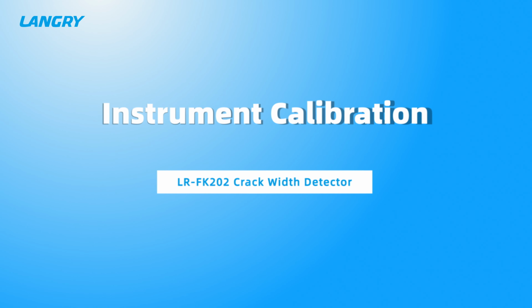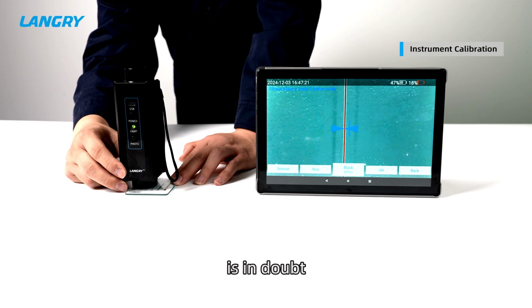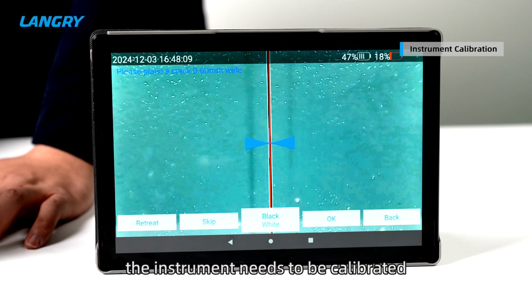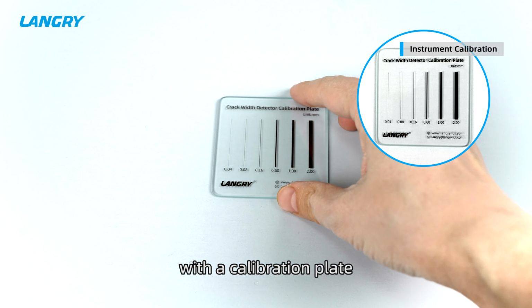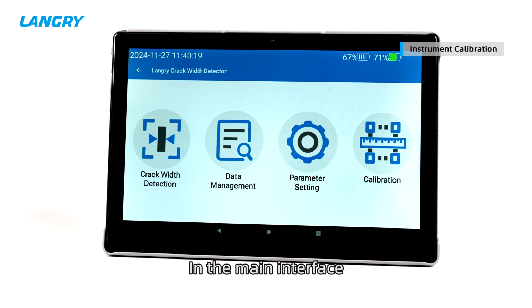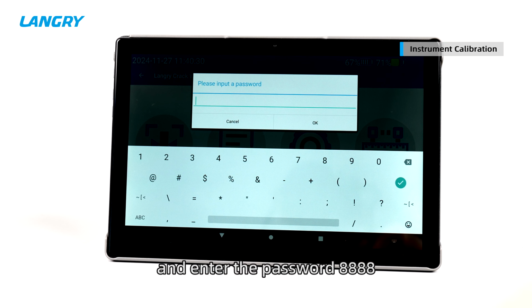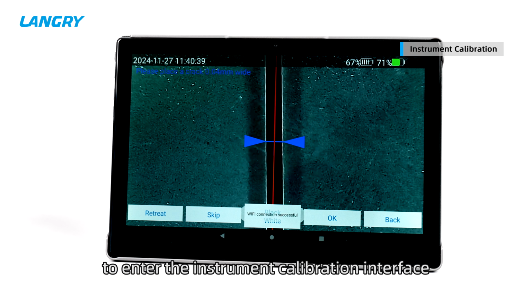7. Instrument calibration. When the observed value of the crack width is in doubt, or when a different probe is replaced, the instrument needs to be calibrated. Instrument calibration should be carried out with a calibration plate. In the main interface, click Calibration, and enter the password 8888 to enter the instrument calibration interface.